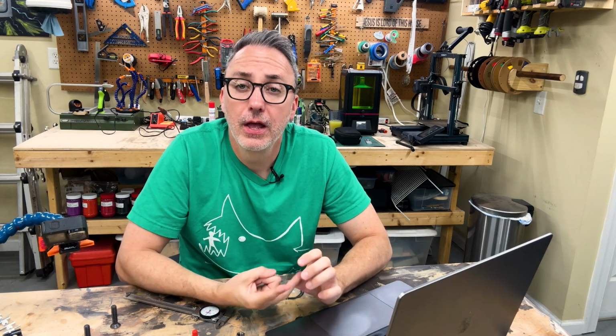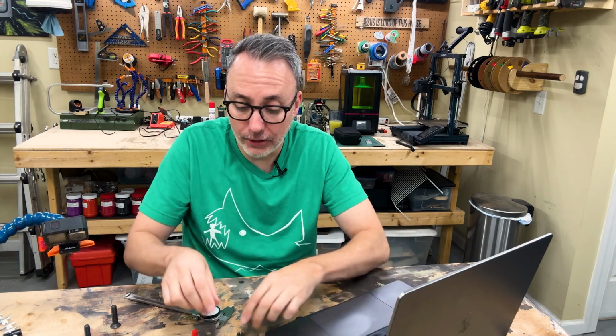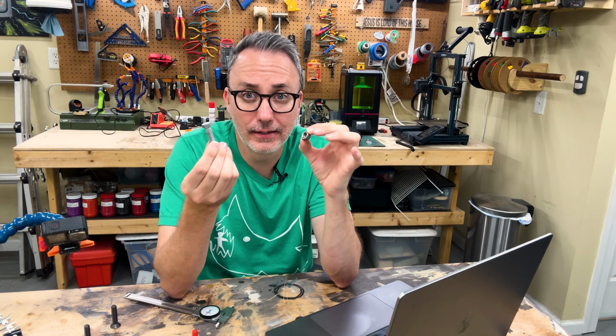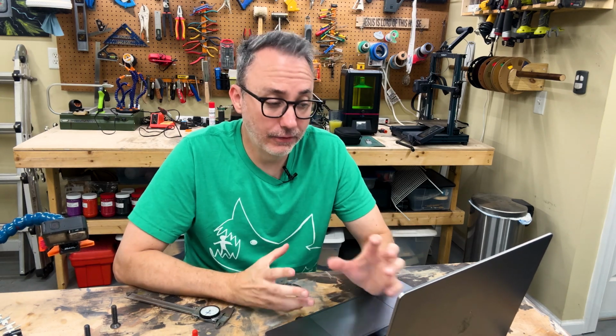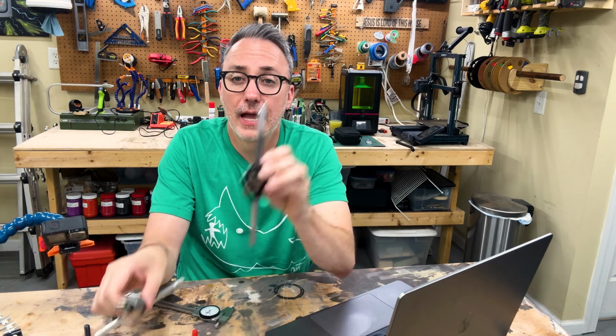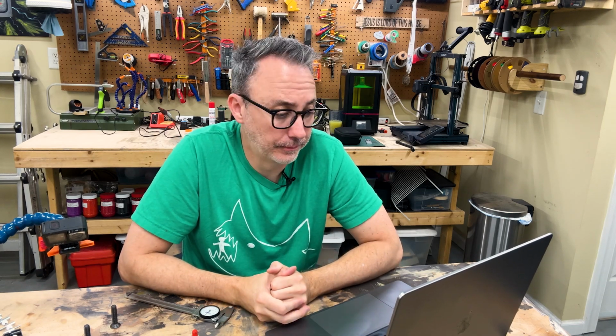All right, so let's review. We've gone over the history of the thread, how to know what kind of thread you're working with, how to 3D model a thread using the thread tool and the hole tool, and we've 3D modeled a recreation of this bolt and this nut. And we talked about giving clearance to your nut and your bolt in Fusion 360, or using a tap and die in order to give you the clearance you need for it to actually work. All right, so that should give you all you need to make threads in your 3D printed parts.